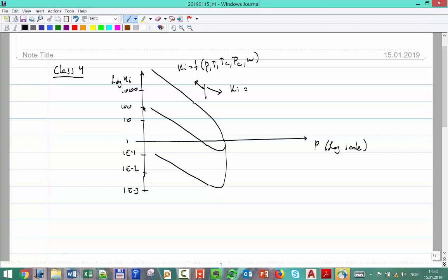Ki becomes also a function, on top of all the other things, P, T, Tc, Pc, and omega, of what other components are in the same container, what components you have together. So in other words, it's also a function of the composition. The way methane behaves, or the way methane splits, and ethane and propane and the rest, depends how many moles of methane you have, how many moles of ethane you have, and so forth. So to avoid that complication, we have removed that parameter.